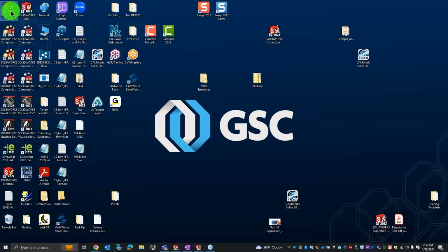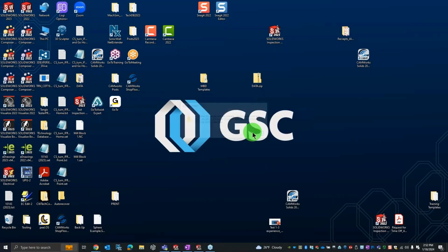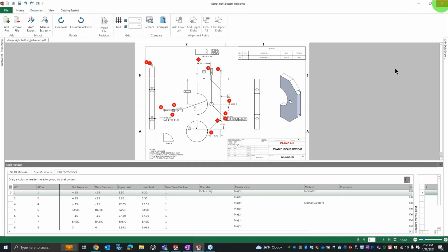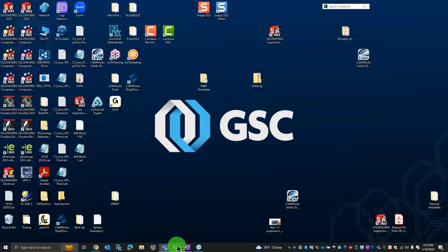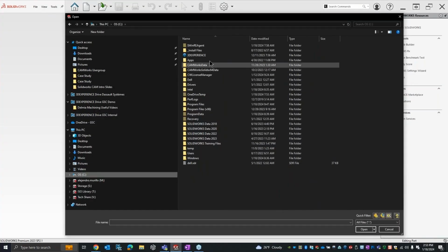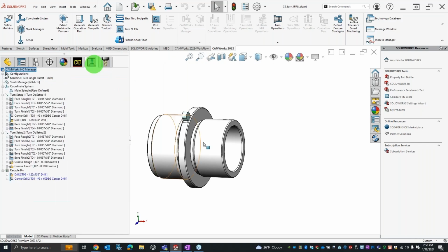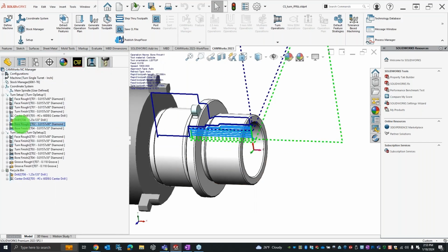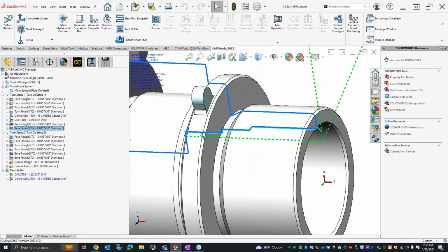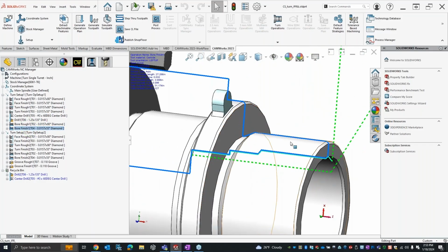One. Okay, let's see if I can show you something. I'll pull up a real quick example. You should be able to control how much it clears out from the bore using those NC options. It looks like I already had the software open. Let's open up a quick example from some training files. This part has a bore in it. Let's do the bore finish to make it simple. Can you see that okay, Louis? Yes, I can see it.